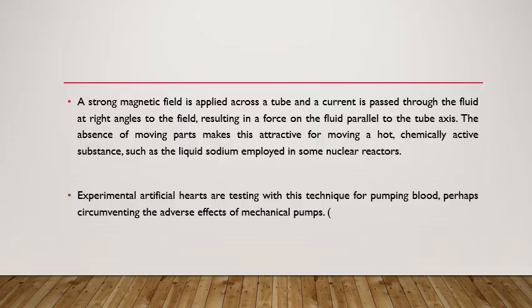A strong magnetic field is applied across a tube and current is passed through the fluid at right angle to the field. This results in a force on the fluid parallel to the tube axis as shown there. The absence of moving parts makes this attractive for moving a hot chemically active substance such as liquid sodium employed in some reactors.